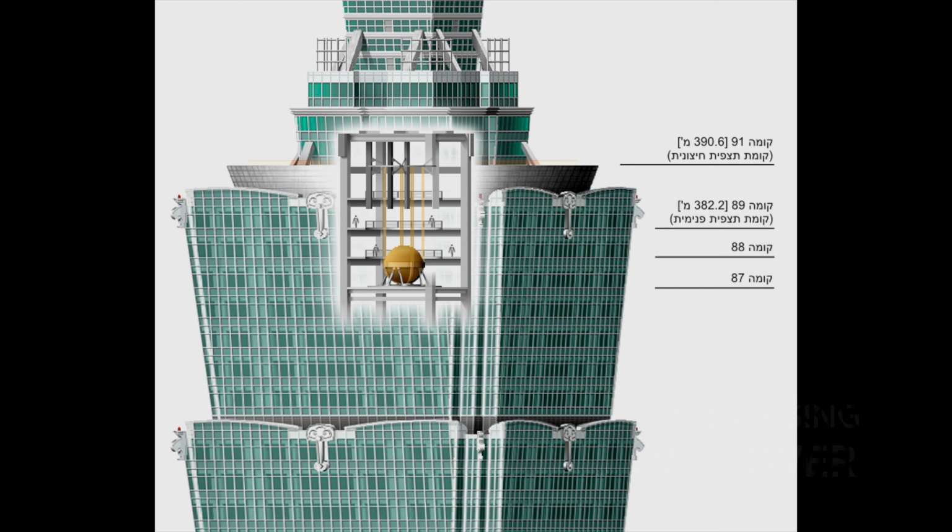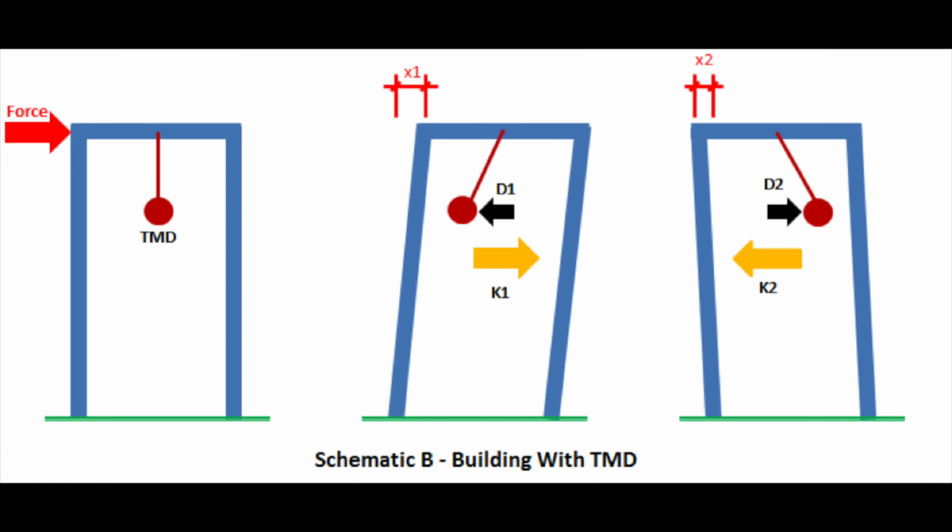For the final case, we will be looking at the damping mechanism using pendulum power. One of the damping methods that can be implemented is known as pendulum power, used primarily in skyscrapers and high-rise buildings. Engineers suspend a large ball with steel cables with a system of hydraulics at the top of the buildings. When the building begins to sway, the ball acts as a pendulum and moves in the opposite direction to stabilize the oscillation. Like dampers, these features are tuned to match and counteract the building's frequency in the event of an earthquake.